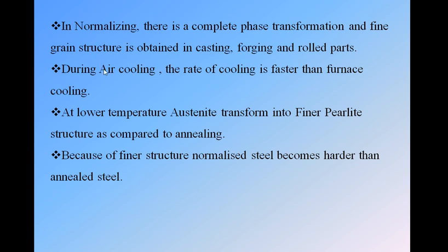Next, during air cooling, the rate of cooling is faster than furnace cooling. What is meant by rate of cooling? It is the cooling speed. As we know, in a furnace it requires more time for cooling. In air it requires a shorter time period for cooling. So the rate of cooling is faster than annealing or furnace cooling.